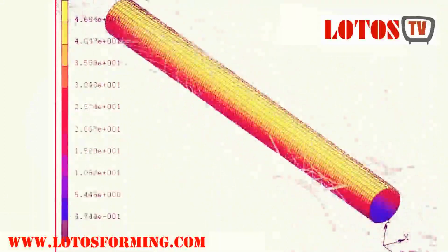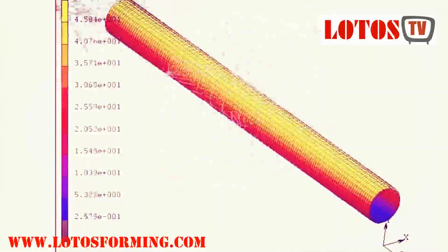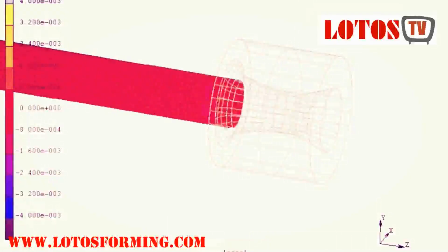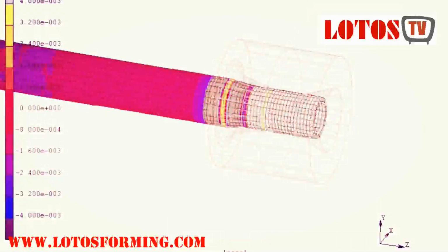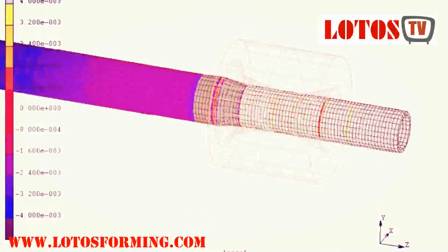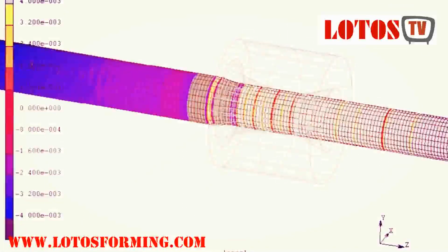Theoretically, we can still use this approach to do that, but in order to do that, we need to develop very large rolls and also a large plate to perform this dimpling process. And from the large dimple strip developed, we can then cold-form it into a section, and from that section, we can perform mechanical tests, depending on the application.